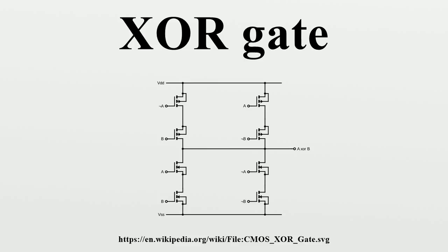Correlation and sequence detection. XOR gates produce a 0 when both inputs match. When searching for a specific bit pattern or PRN sequence in a very long data sequence, a series of XOR gates can be used to compare a string of bits from the data sequence against the target sequence in parallel. The number of 0 outputs can then be counted to determine how well the data sequence matches the target sequence. Correlators are used in many communications devices such as CDMA receivers and decoders for error correction and channel codes.